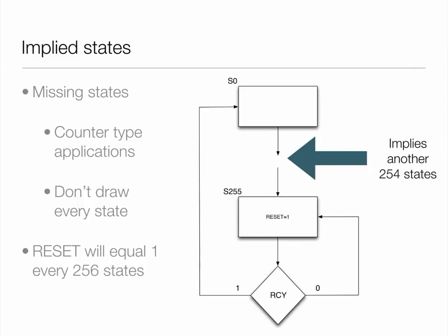Now, you could go off and build that, but I can tell you now, it'll use at least 8 D-type flip-flops, and you can do it in less. But that's because you have a repertoire of tricks, ways of doing this. You can see you need an 8-bit number to actually store the state. As I said, there might be other, cheaper ways of doing things. Right, okay. Next slide then.